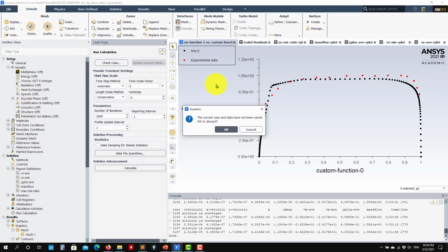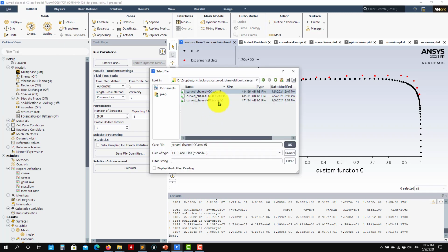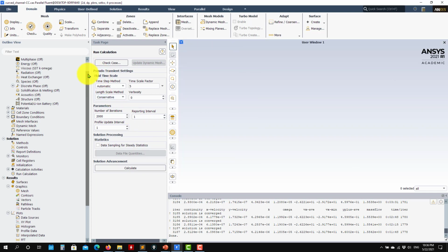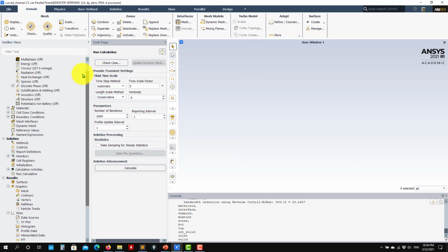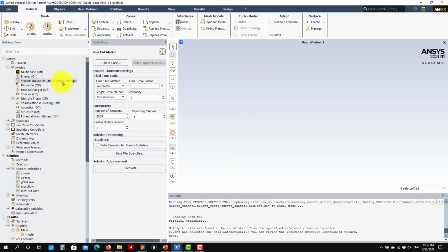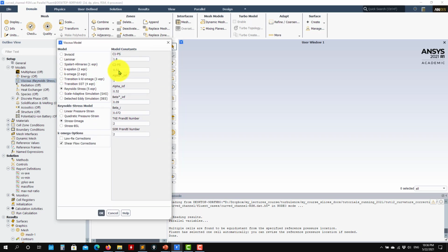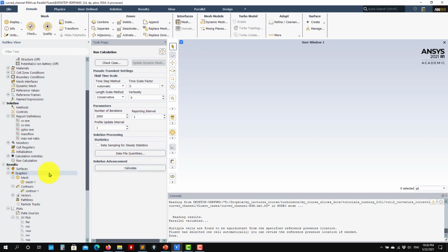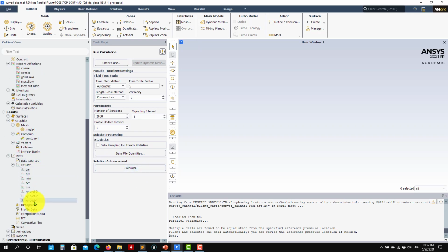So now let me compare with the Reynolds stress model, okay, RSM. And what is interesting is that, remember, the Reynolds stress model is an anisotropic model, so it doesn't suffer from these, let's say, limitations or deficiencies that you find in the eddy viscosity models that are isotropic. So see that there are no corrections here, okay, no production or curvature correction in any of the formulations, okay? So here we have this value here, so let me plot, we have already the solution, so no need.